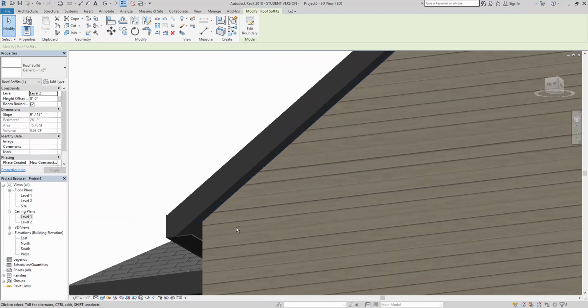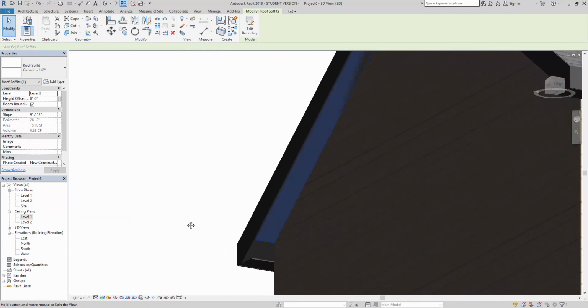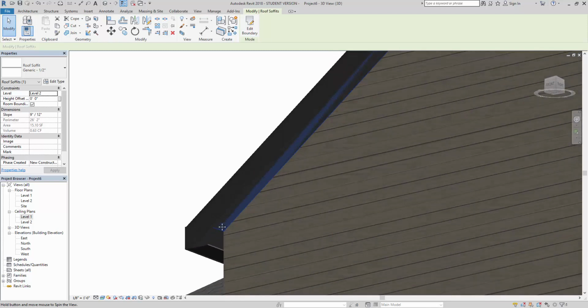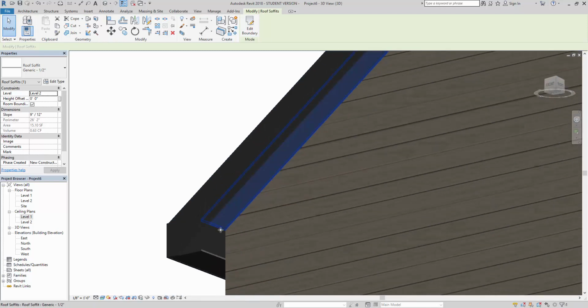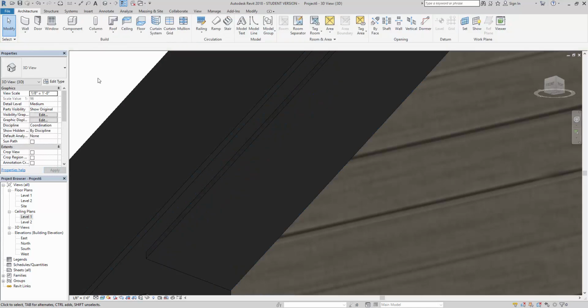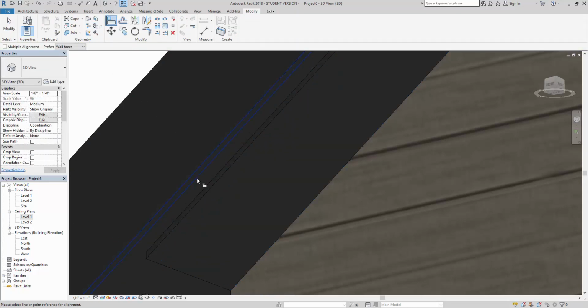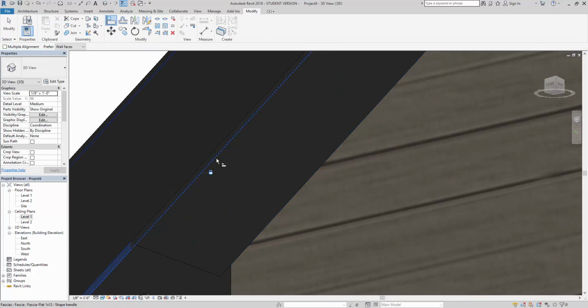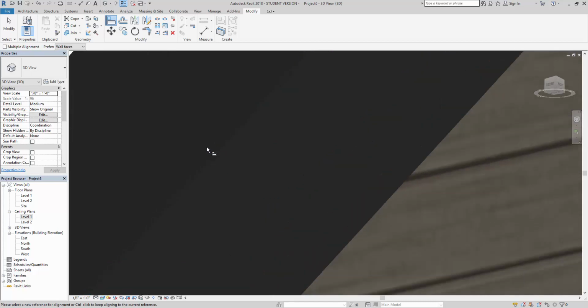And there it is. You can see it's phasing right now because it's at the same surface as the roof. So it needs to come down just a little bit, and then we can use the align tool to do that. We'll just go -6 inches. That brings it down to where we can see it. And we can align and lock it.